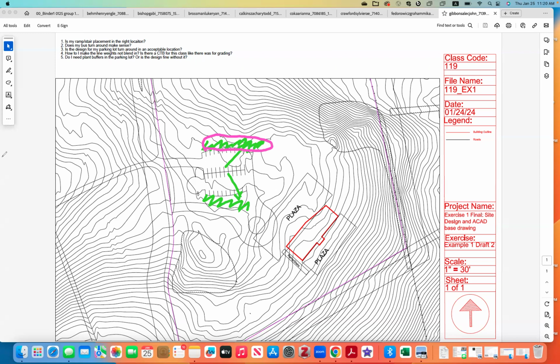If you do not direct water to the side, and instead later create a swale in the middle of the parking lot, then you need to think about adding a medium of vegetation in that area. Or you could direct water like this, which is another option.